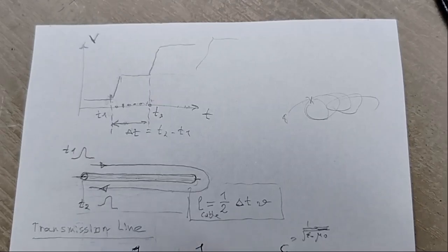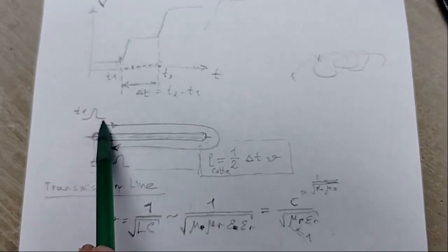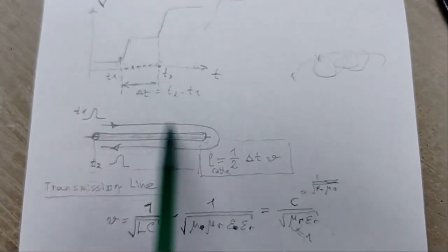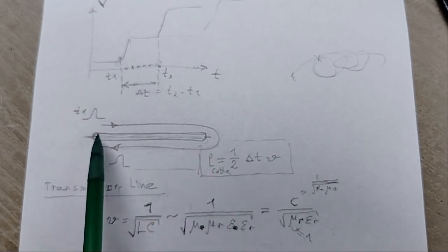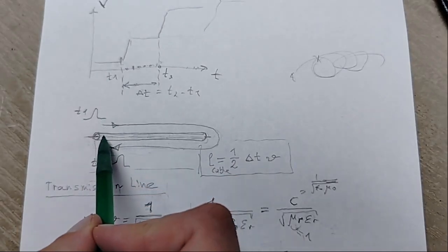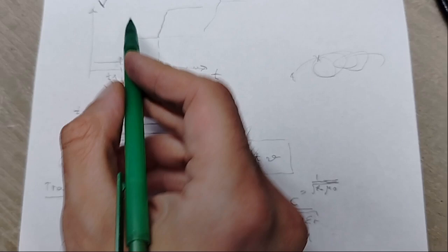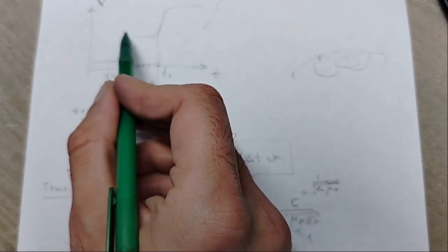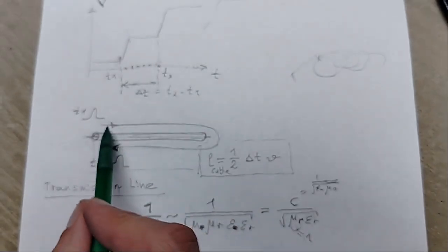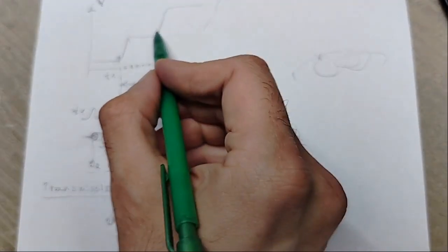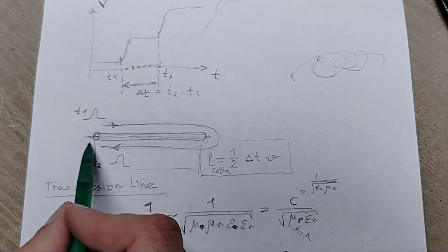Let's discuss our measurement results. So the signal travels along the cable, goes to the end of the cable, and then reflects back to the initial position of this cable. And we can see it on the graph. So this is on the oscilloscope. This is the initial moment when we have the signal coming into the cable. You can observe it. Then we have a plateau. Signal goes like this, and then we have a bump. Signal goes back to the initial position.